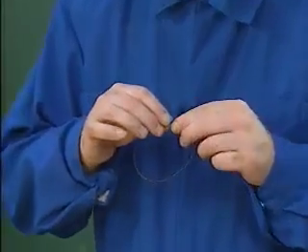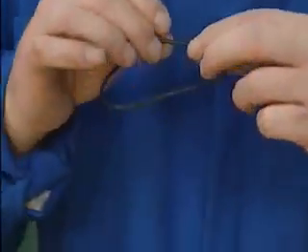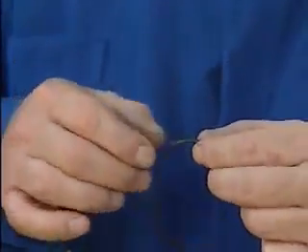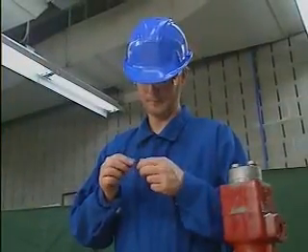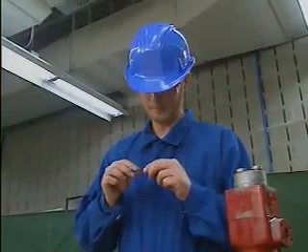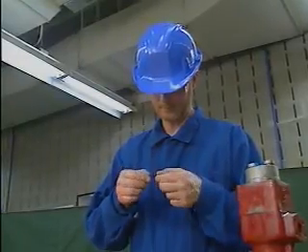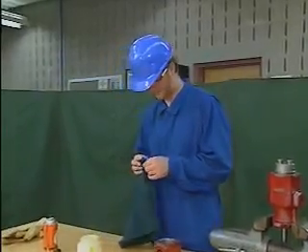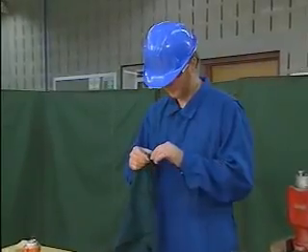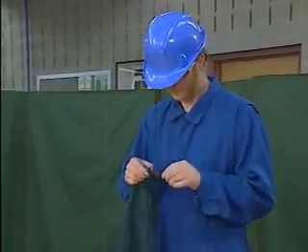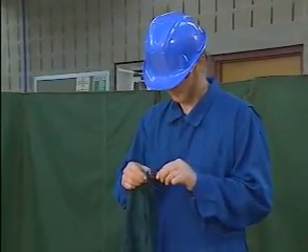If the O-ring is damaged, it may not seal properly and should be replaced. Even slight damage or irregularities in an O-ring could prevent it from sealing properly, or could cause the O-ring to fail prematurely. This O-ring is not damaged, so the mechanic can continue to the next step, which is lubricating the O-ring.